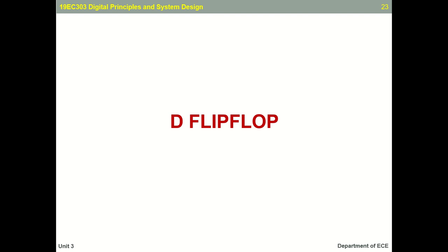And why this D flip flop has been designed is, we know that this D flip-flop is a modified version of your SR flip-flop. It can also be a JK flip-flop too. Okay. So in an SR flip-flop, a condition that may prevail is called your race around condition. When both your set and reset inputs are equal to 1 and 1, then the flip-flop will be moved into a state called your indeterminate state. So here, this D flip-flop is an alternative form of SR flip-flop which removes the race around condition.